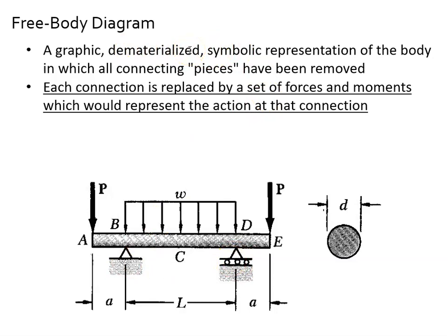Dematerialized, meaning we don't care if it's concrete, steel, or wood. We're just trying to figure out the geometry of the different loading types and how the math works out, like how these loads up above are getting to these supports down below. Each connection is replaced by a set of forces and moments that represent the action at the connection.